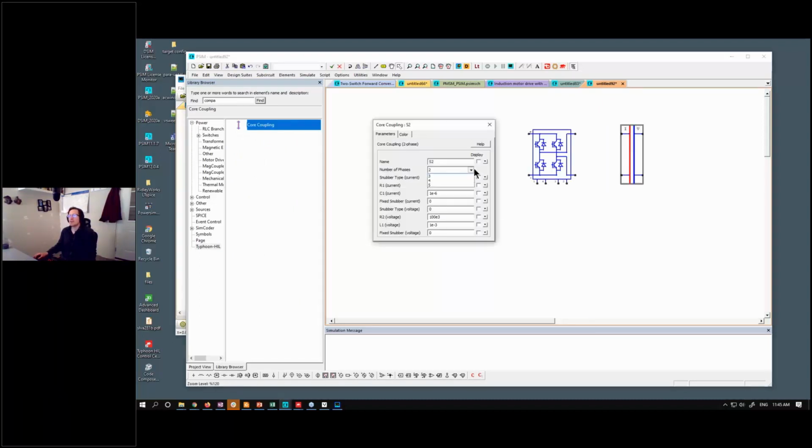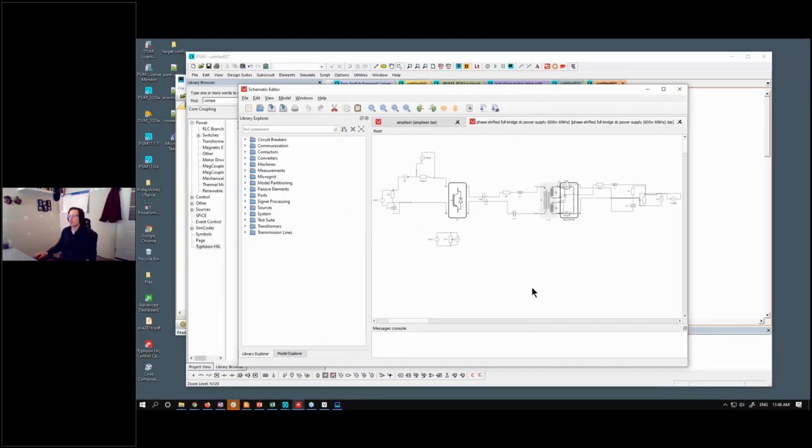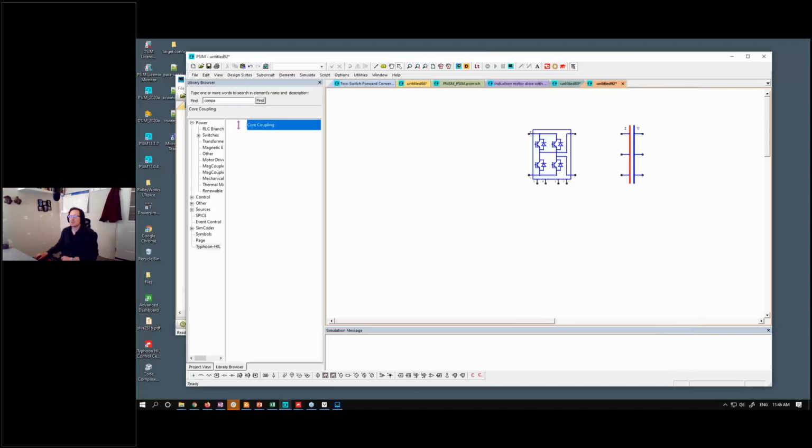And what this is going to do is it's going to help you partition your simulation properly when you move it to Typhoon. And so when you click the Typhoon button up here, it's going to export it out to the Typhoon system, and it's going to look like something like this after you've exported. So then you can just compile this and launch it directly on the HIL system. So this is just the power stage. Let's look at...